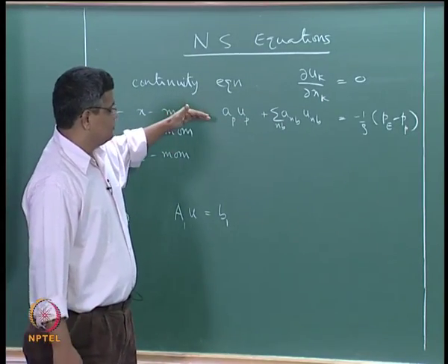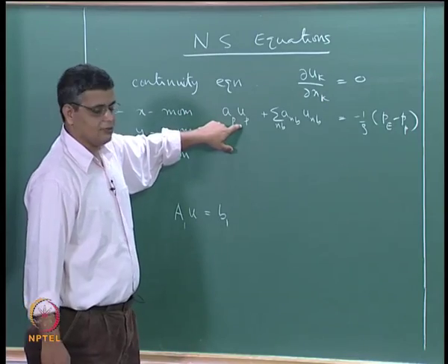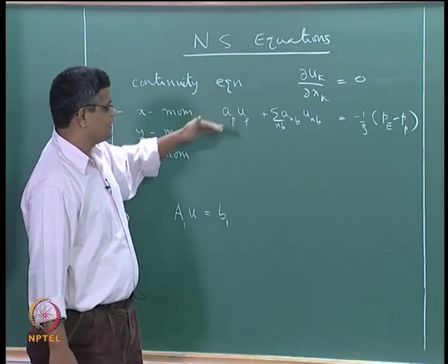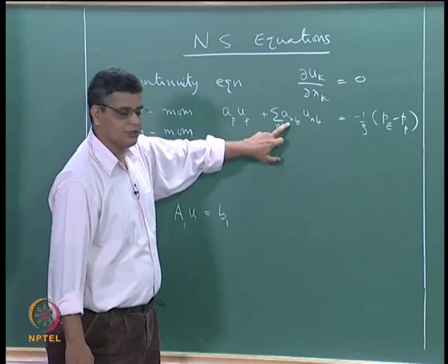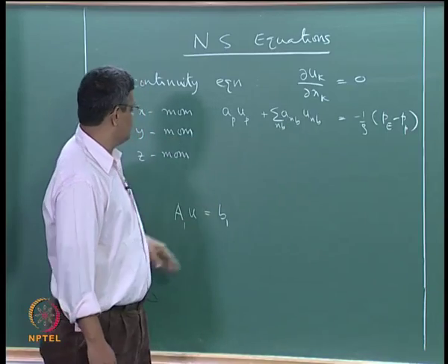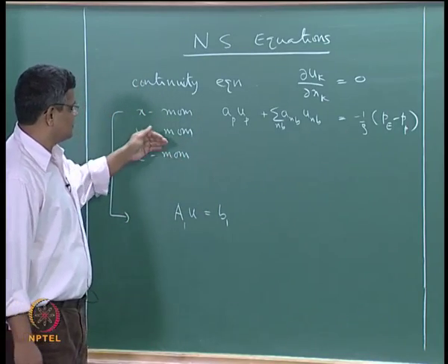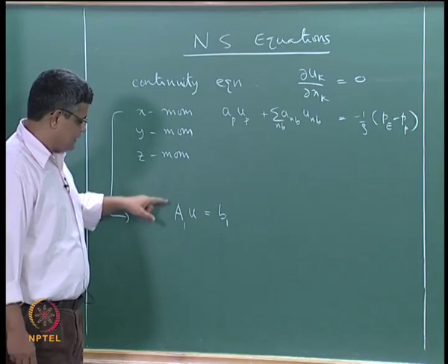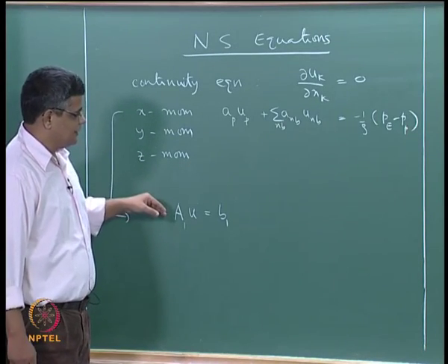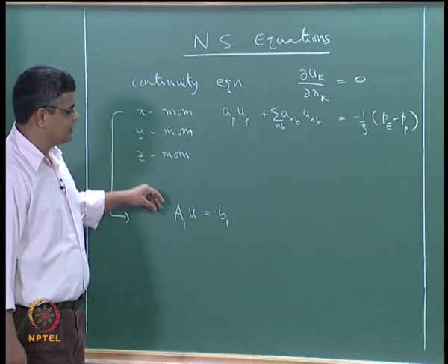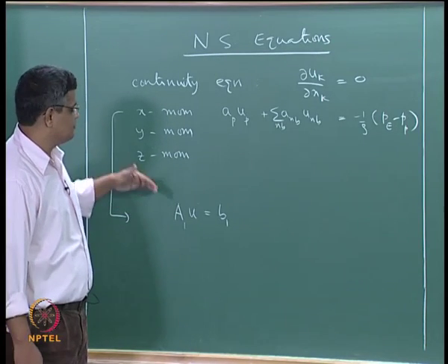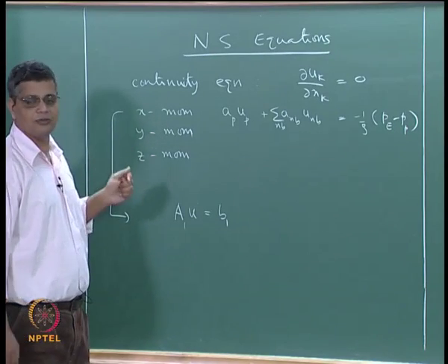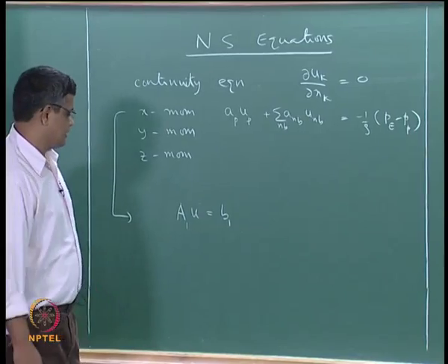And we notice that if you want to solve this equation, then we need to know the neighboring values, and not only that, for the general case these linearized coefficients also contain the velocity components of the y momentum and z momentum. So in that sense, this A1 here contains approximations from linearization and approximations from the current estimate of the values of the v and w components in the x momentum equation.